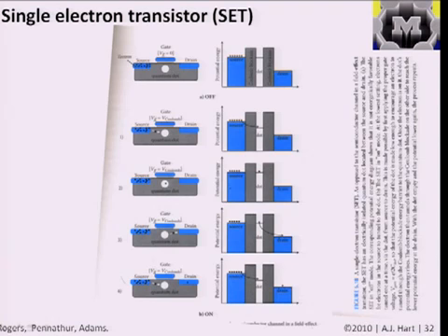And because we know that the quantum dot has this discrete set of allowable energy levels, you can basically create space to store one extra electron in the quantum dot itself. And what happens is, as you then apply a second voltage difference between the source and the drain, you can store one electron at a time on this quantum dot and then let it tunnel across to the drain electrode and shuttle discrete numbers of electrons across this island.